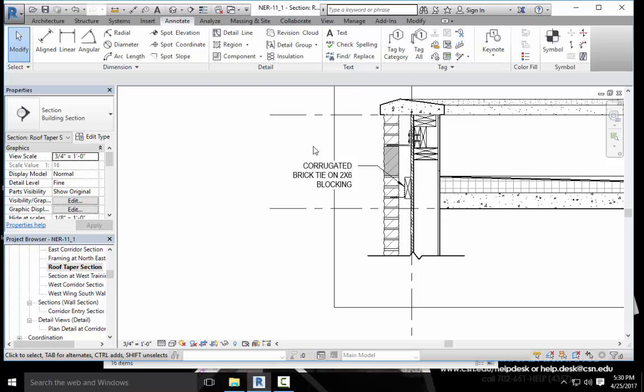Over the years, Revit has been labeled as a poor drafting application. This is unfortunate because it can be a good drafting application when given the chance. The only challenge is to figure out where to start. The objective of the next procedure is to create a blank view and then simply learn how to draw lines. On the View tab, click the Drafting View button as shown in figure 11.50.